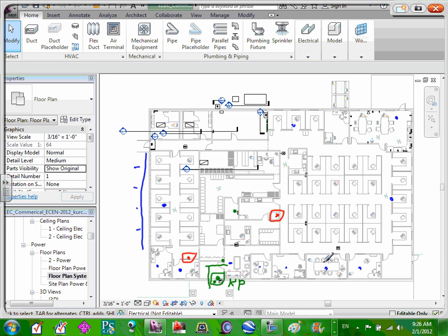So kind of number 6, we say main staff keypad in main entrance vestibule. Well, like I said, picture yourself walking into this building. You need to be able to get in the entrance, and you need to be able to disarm the system. So that's really 2 keypads. You have an exterior keypad that gets you in the doors, disarms the magnetic locks. You get in, and the security system is beeping. It gives you 45 seconds to enter your code, or the system goes into alarm.